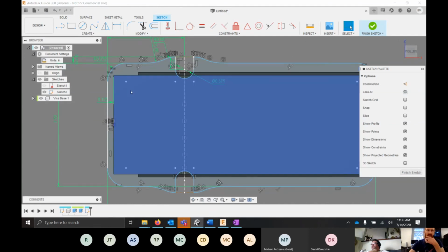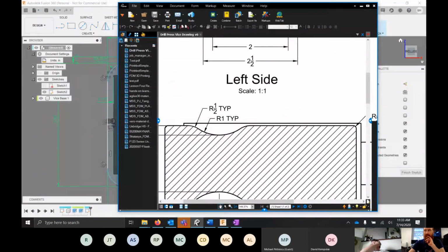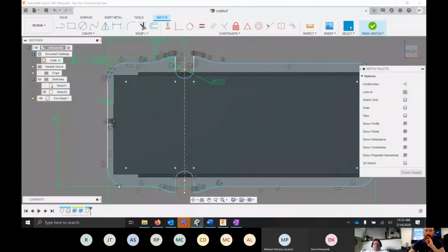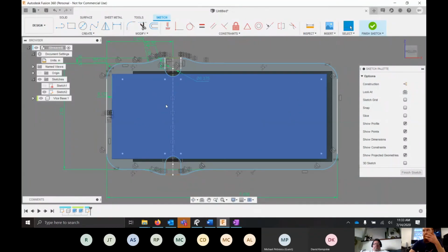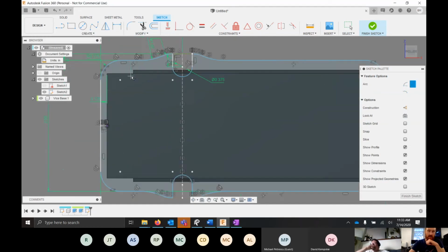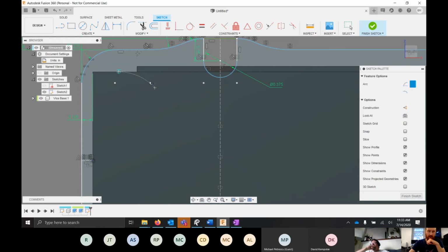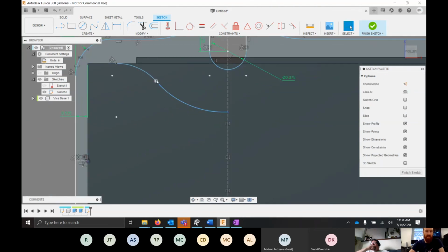So the only thing that we now need to add is also a little cutout section for our casting here. So I'm just going to add this to the same sketch so that we can use this center line to make this easier. So in this case, again, we'll go to create arc, and I'll draw in a 3-point arc here, let it take its tangency, and I'll take a 3-point arc here, and I'll let it, nope, it didn't quite. That's okay. We'll just apply a tangency here.